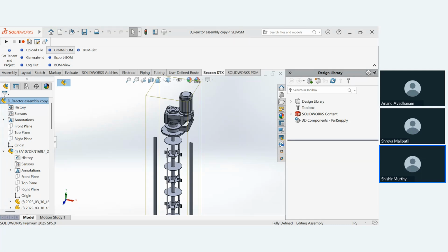So once you define product code, you get this plus icon which you see here on the BOM editor window right here. So this plus icon enables us to add new items below this. So if I have any sub-assemblies where I want to add more child, I just create an item code which has associated item code which has a product code to it, and then be like, this is assembly, and to this I want to add child. But for this example, I'll just select this and I say create a child. So you can see at the bottom, I got a new entry text box here. And I can just type in carton that I just deleted for the packaging purpose.